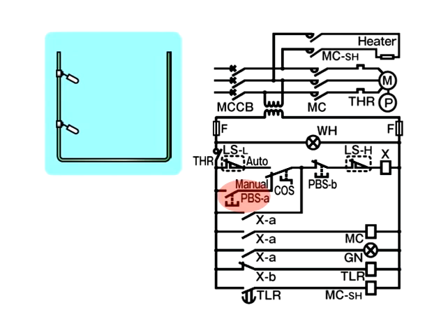As the push-button switch PBSA is pressed, a current is passed from PBSA to changeover switch COS, to push-button switch PBSB, to high-level float switch LSH, and to the coil of control relay X. Thus, the coil of X is excited.